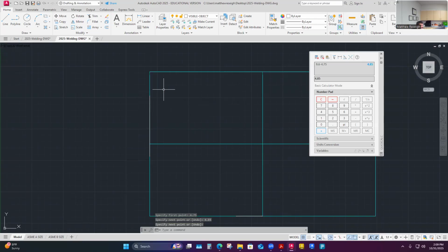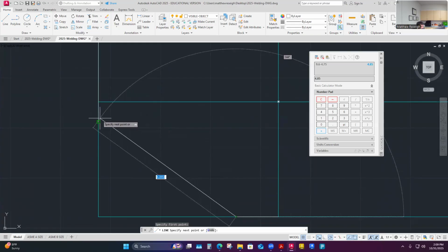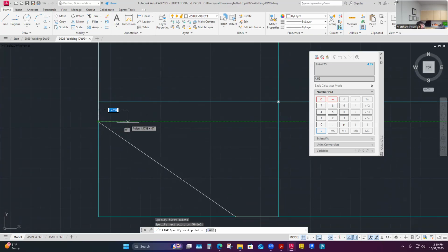So that's kind of where that radius will start now, right? So let's go back to this and hook this together. Where those two, this one and this one, I just need to draw a line connecting the two together. So I'm just going to go into my line command on that visible layer and target that grip that I can kind of see show up, and then target this grip, bam, like that. That's a left click and a left click. And then I'm just going to hit enter or right click, enter.